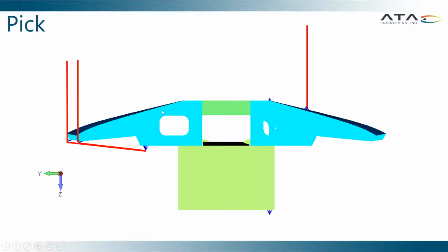I have started out this lift by attaching a chain to a lug on the hull right here. And I've also got a couple of lugs on what is currently the underside of the ship section. I'm running chains from those lugs up around this corner and vertical from there. And I've put a couple of chafing guards in here to protect the corner. Like I said, this is probably not the best way to lift this, but this is how I chose to do it for the demonstration.